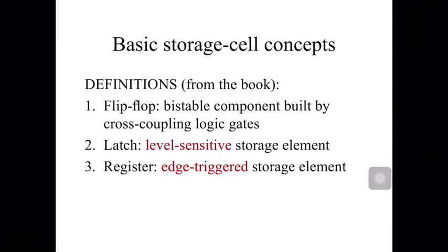As you can see here, these are the three basic storage cell concepts. The first block is the flip-flop. It is a bistable component, and it is usually built by cross-coupling of logic gates. The difference between a flip-flop and a latch: a flip-flop can be either level sensitive or edge sensitive. A latch is always a level sensitive storage element, and a register is an edge triggered storage element.